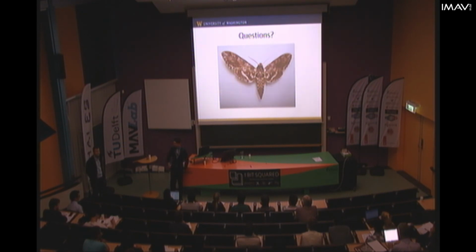The question was how do aerodynamic forces, or how can we possibly incorporate them into the model? Good summary? The answer is it's difficult to say. The reason that we've neglected it ultimately was there was some amount of experimental evidence in the past, an experiment where they actuated this in both helium and air, at least the Hawkmoth wing, and found that the deformation presumably was due to inertial elastic effects. So that's kind of the background as to why the assumption was made.